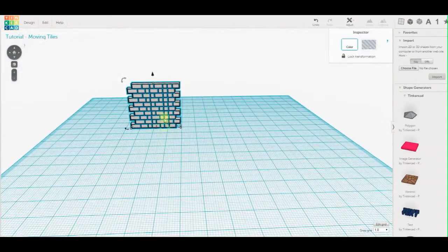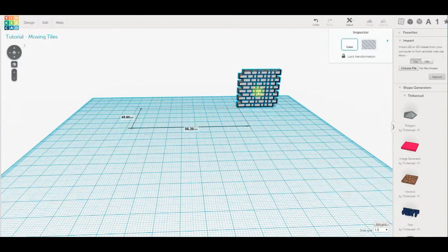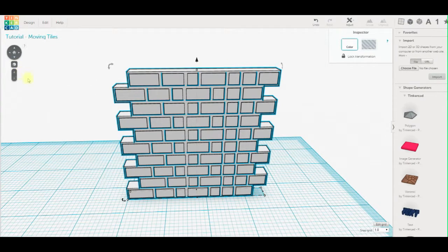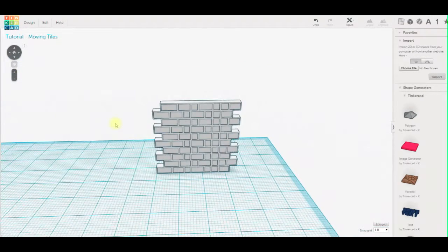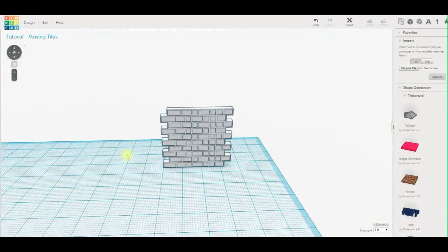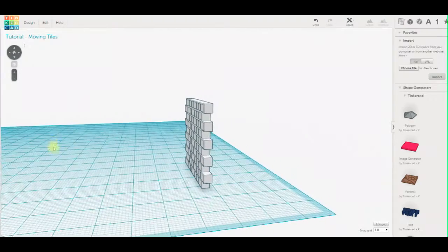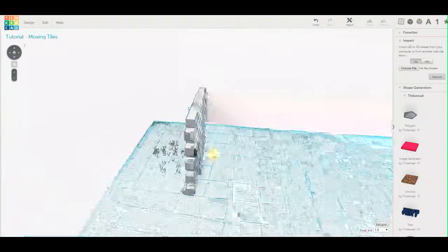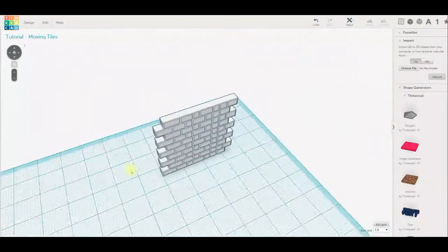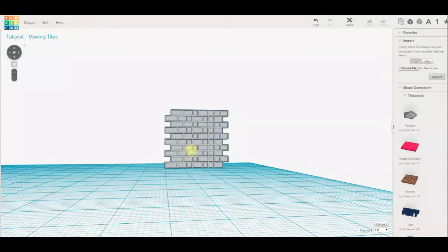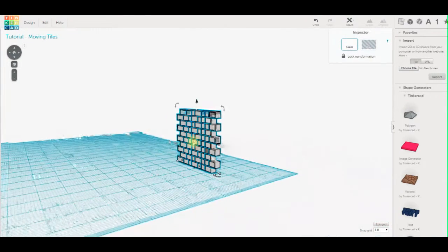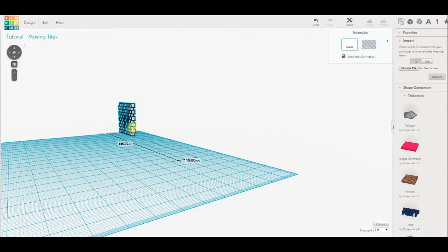Now you might find yourself moving your parts out of the way while you're trying to work on it, and you can't see it. This little square box here will take the screen view straight up to that part, that area that you're working in. Rolling your mouse wheel one way rolls you out, and the other way moves you in. Right click and hold and drag will rotate your view around the part. And again, just drag the part itself by holding and dragging. It will always stay flat on the blue plane that we're looking at.